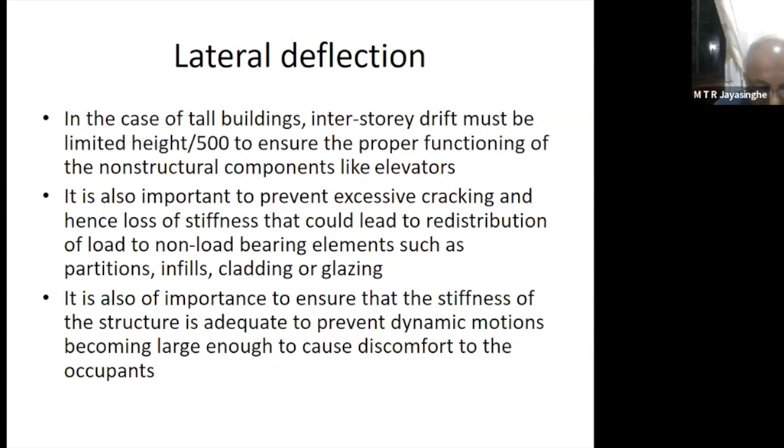Concrete is much weaker, but concrete is made of natural materials like the crushed stone, sand, all that we can find around us, plus some manufactured material again using the natural materials, and that is it. In addition to that, we can have byproducts like fly ash, we can also have silica fume, and we can also control the water cement ratio significantly by adding very advanced admixtures.